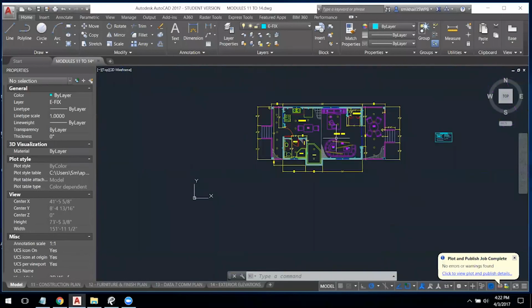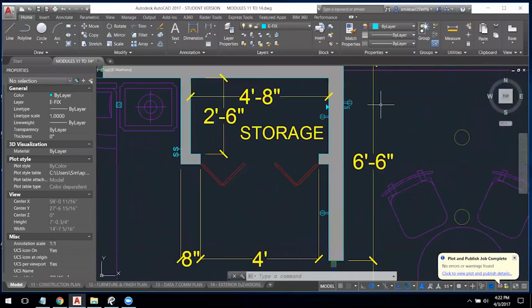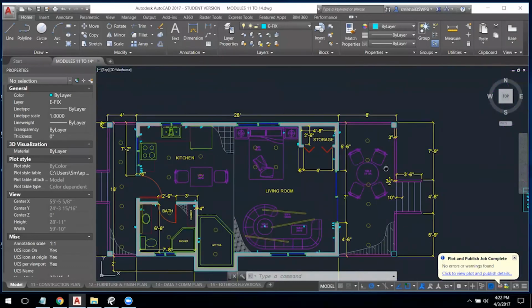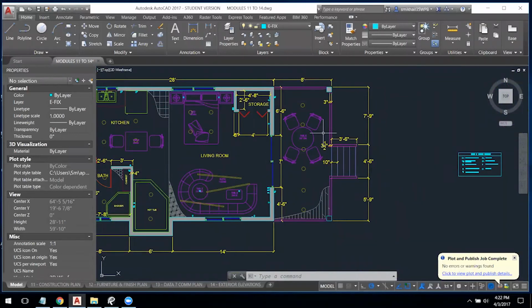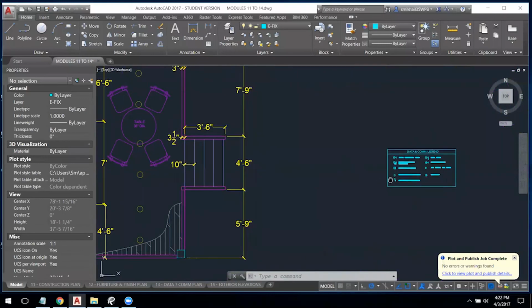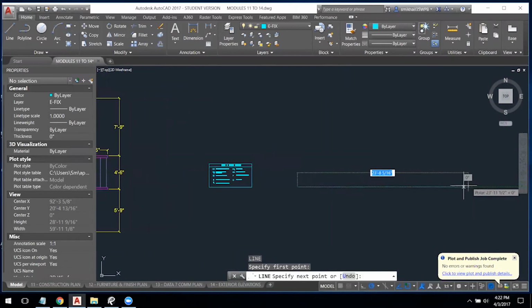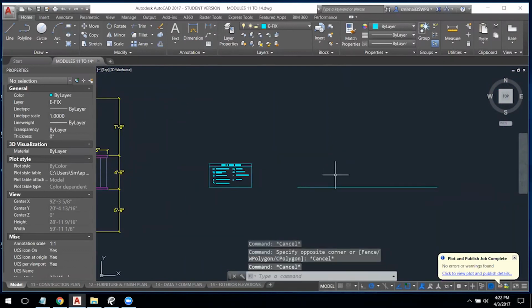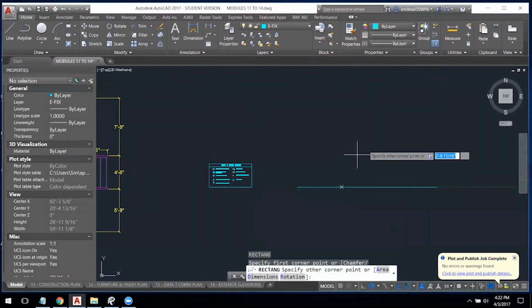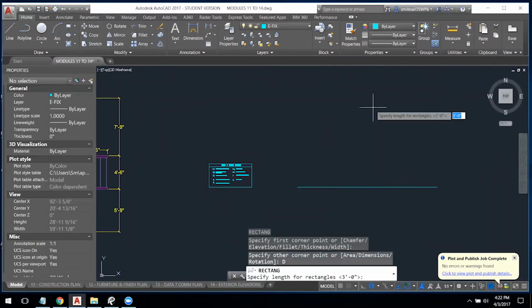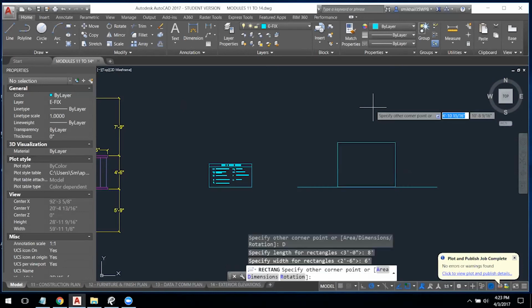The last piece of the puzzle is the heights of these fixtures. So by default, generally, we create a small sketch that will give us the typical mounting heights, unless otherwise noted. The way this works is that we create another legend like this at full scale. So we'll draw a line that is basically the ground floor, and I will draw in another rectangle in here. The dimension would be perhaps 8 feet high. And then I'll make a wall that is generally about 6 feet wide. Okay.